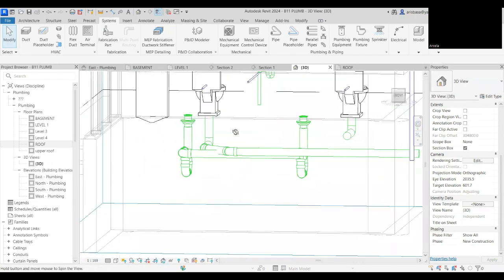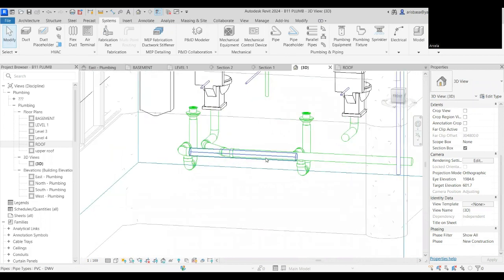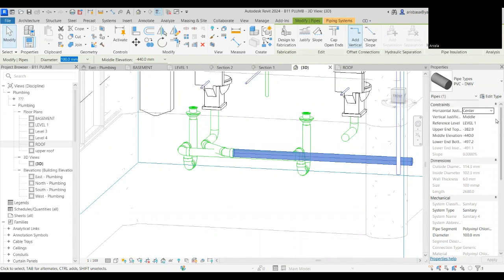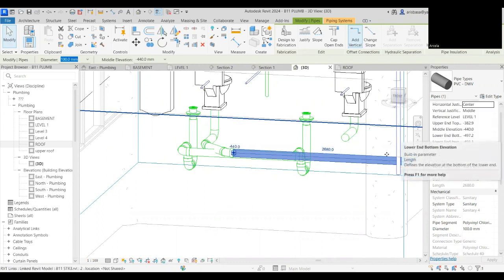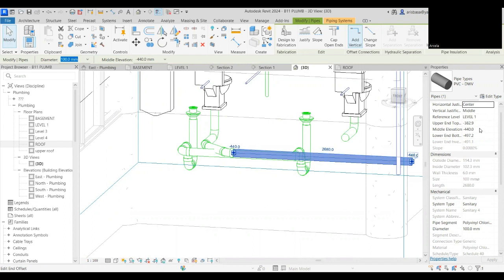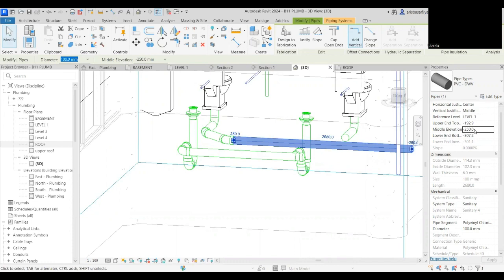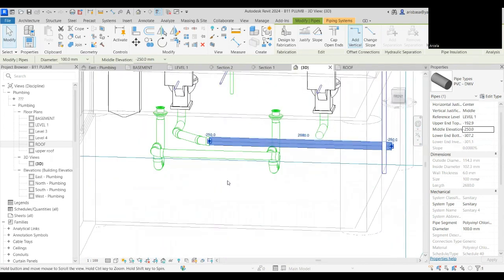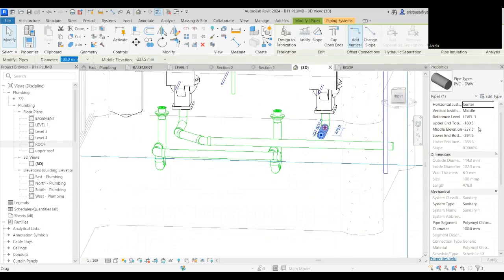And we don't need to get this to connect to. Oh, these pipes are tangled already. We need to move this up. Let's change the height of this. So actually the middle elevation is 400. Now we'll change the middle elevation, make it minus 250. It will go up on its own. So see, you change the value there. So now I think it will match it. So this also will make it minus 250 now. Middle elevation minus 250. It is now matching.